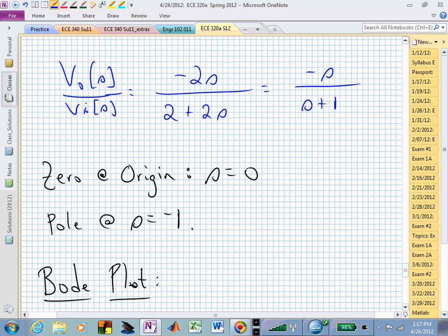So I have a 0, I have a thumbtack in the S-plane, right at the origin, and now I'm walking up the imaginary axis, and I'm actually wanting to look in the positive real direction and have my angles determined from that location. There's the origin. What's the angle from that point up to me? So if I was down here at the origin and I needed to look up at j omega, what angle am I turning through? 90 degrees.